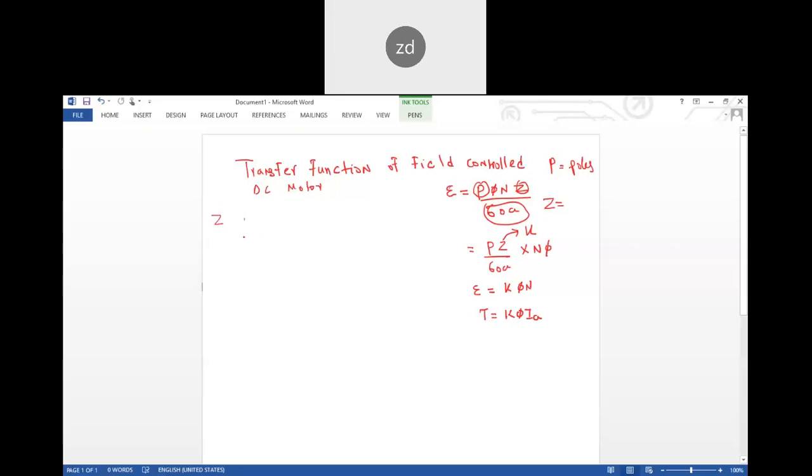you see there is one side of the coil which will have one turn, and another side will have another turn. So Z would be equal to twice T. This is basically, for the motoring, the number of conductors for a single phase. Obviously, this is a DC, so it will be only this. So 2T would be representing Z, where N is the speed and A is the armature parallel path.